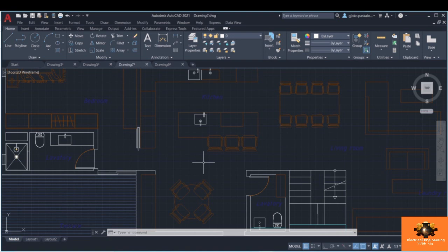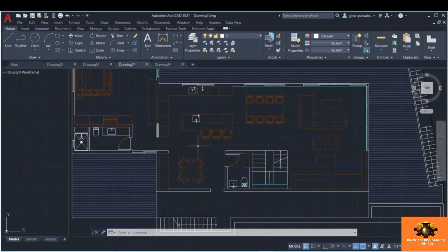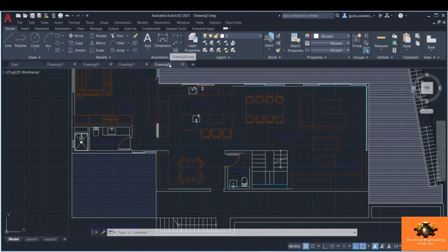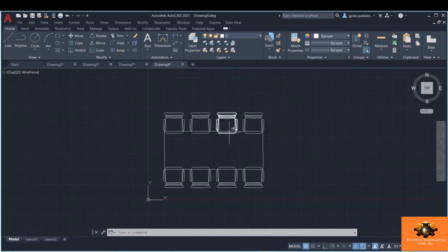Now let me go ahead and show you how to create, insert and modify your own blocks just to get the hang of it, and for that I prepared something, so let me go ahead and show you. In here we have this predefined drawing. As you can see, it's kind of complex. It contains these chair blocks that are actually predefined. We have also the table element here, so we are going to create our own block while using this complex drawing with predefined blocks and additional objects.